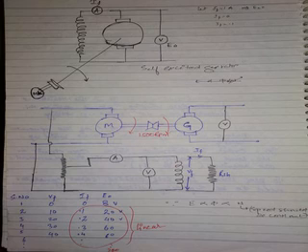So listen. This line you have plotted is VF versus IF. In exam sometimes you won't be given the VF IF characteristics. You will be simply given the shunt field resistance value as 100 ohms. You will be given IF and E0 only. To plot OCC you will be given 4 or 5 points. You can plot OCC and do everything, but you will not be given the shunt field resistance characteristics. You will be just given, let the shunt field resistance be 100 ohms or 50 ohms or 200 ohms.